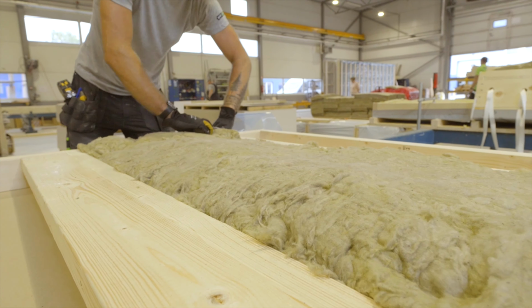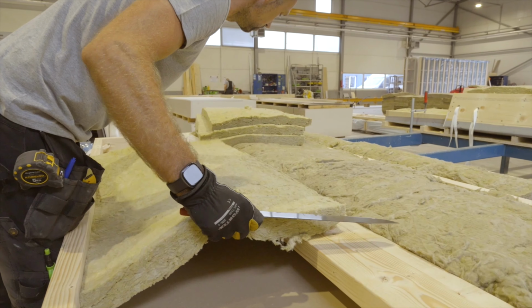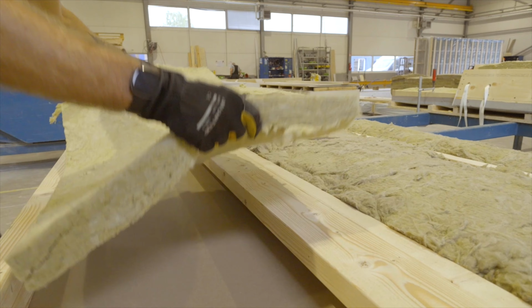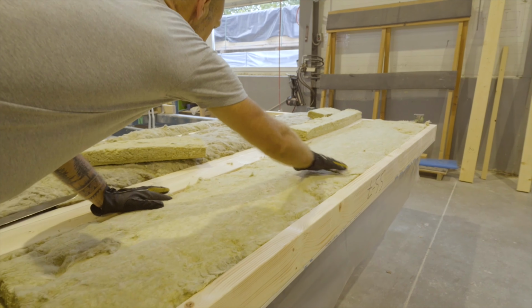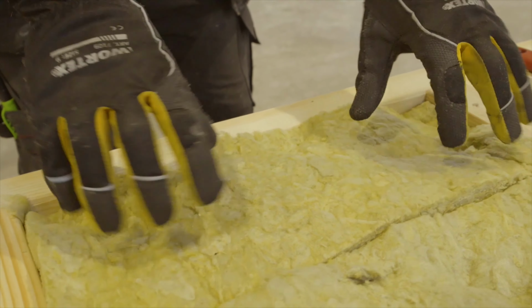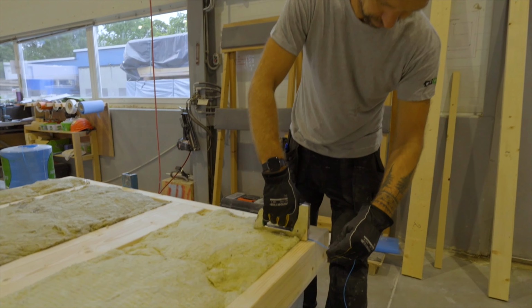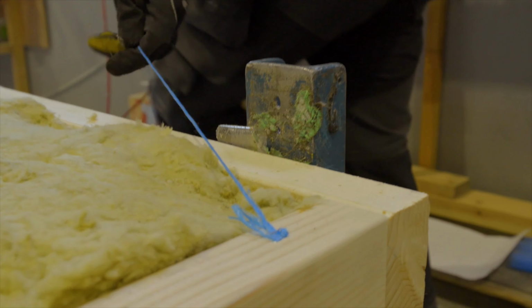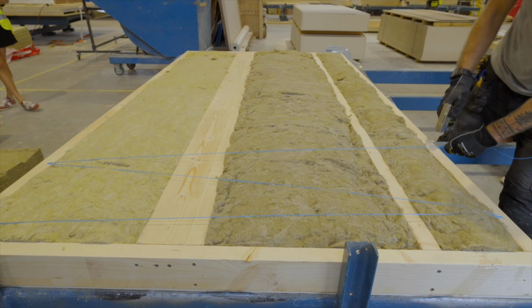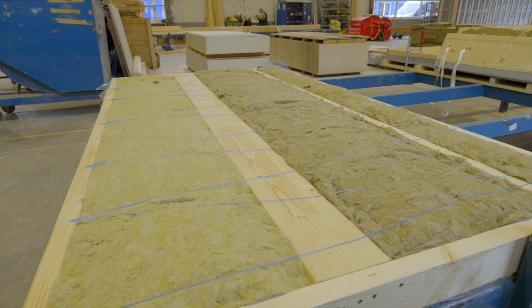formation of gaps. If the insulation is laid in several layers, it must be ensured that the joints between the insulation are not in line with the joints of the previous insulation layer. The wool must uniformly fill the entire frame gap. If the technology requires that one side of the wall element remains uncovered by boards in the factory, then securing cords or wires are used to fix the insulation in place.